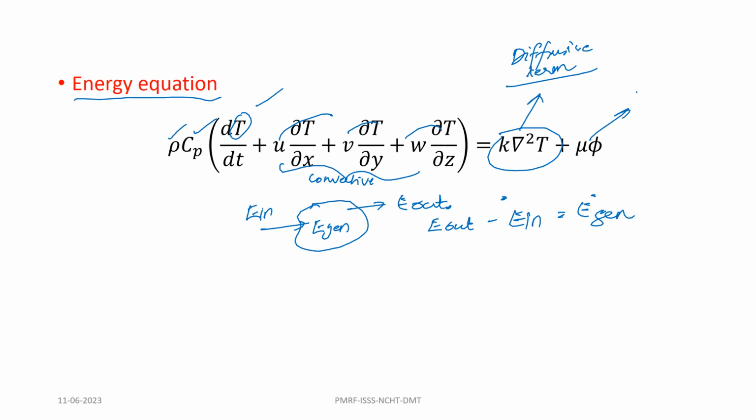Then this part is actually called the viscous dissipation term. So there will be viscous forces inside, and that will be adding up to heating of the fluid element. In most of our discussion, we will neglect this part, because we will assume viscous dissipation to be negligible.